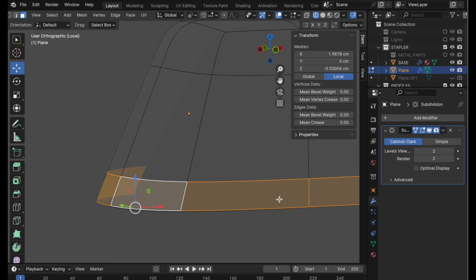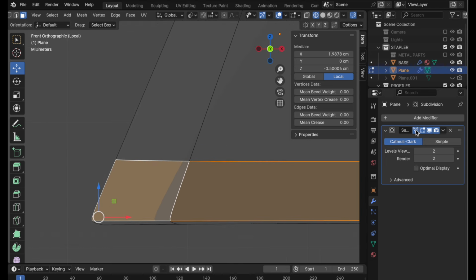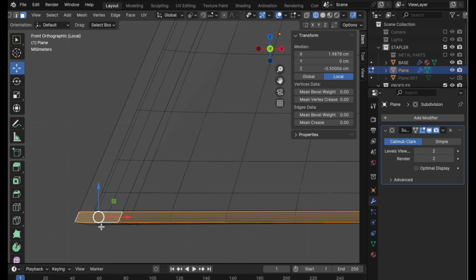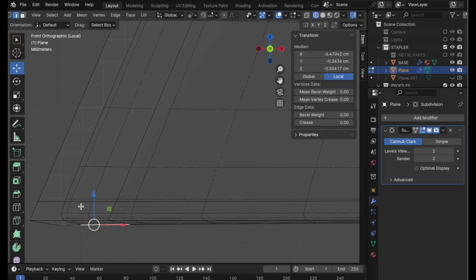This loop going all the way around is thick. These are the subdivided polygons. So if we take a look at this in the front and we go on cage mode, it selects the cage geometry. The subdivided geometry is pulling all the way up here, which means it's potentially pulling shading information, and it's certainly pulling slightly curving geometry all the way up. We don't want that to happen. We want to concentrate it down below.